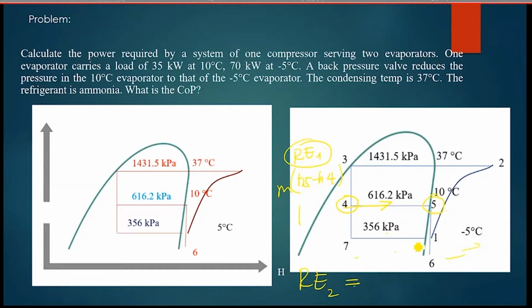Here, right? Yeah. 8 and 7. So H8, which is higher energy because it's going to the right, and then the lower is 7. So here, this point and this point, there's a quantity or distance from point to point. So H8 is higher than H7. If you multiply that with the mass going into this suction at the entry of the evaporator, you will get the mass flow rate of the refrigerant.